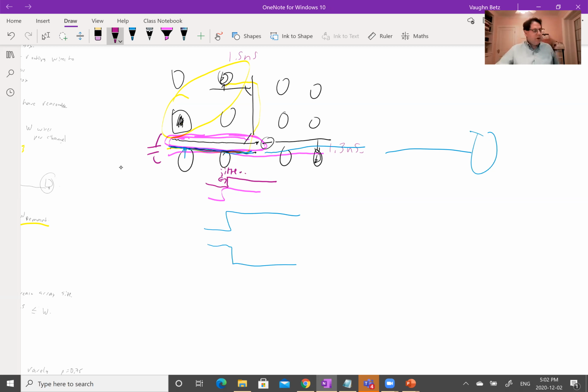So some clock periods, the edge is a little bit early. Some clock periods, the edge is a little bit late. And there are a variety of reasons for that. But one of the big reasons is capacitive crosstalk, so coupling to nearby signals.